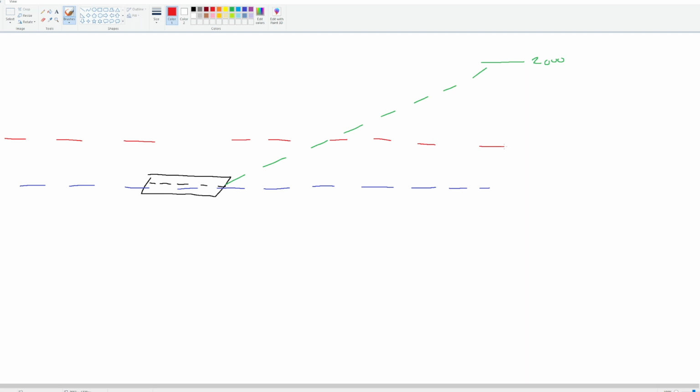So as you can imagine now, if we moved our barometric reference, our mean sea level, we have moved this line, but we have not moved the runway. That means that when we think that we are going to be approximately at this point right here, let's say this is going to be 500 feet. Where is the ground, guys? Well, the ground is right here. So we're going to fly ourselves straight into the ground when we expect the runway here. That is QNH blunder error.